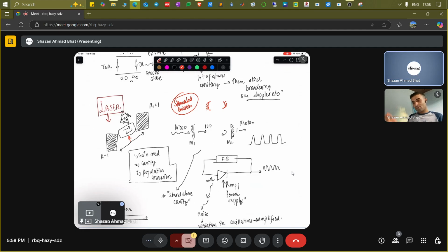These can be just some etched cuts, some semiconductors which are etched at the ends by using certain nanofabrication techniques. They can act like a mirror. So mirror here means something that is reflective. So mostly this is almost like 100% reflective, and this is like less than 100% reflective, so that you have active material, you have some photons coming in, one photon goes in, you have two photons coming out, then that gets reflected, that brings in, this almost like a chain reaction starts.